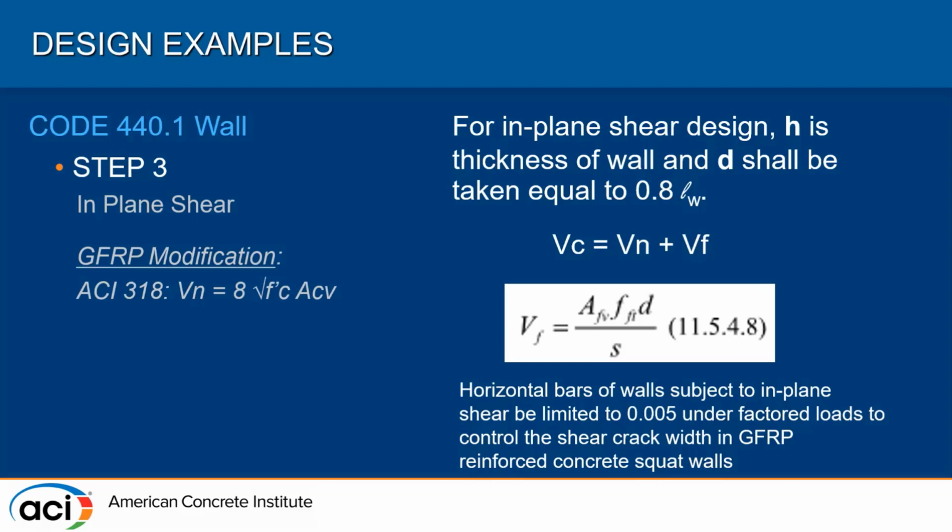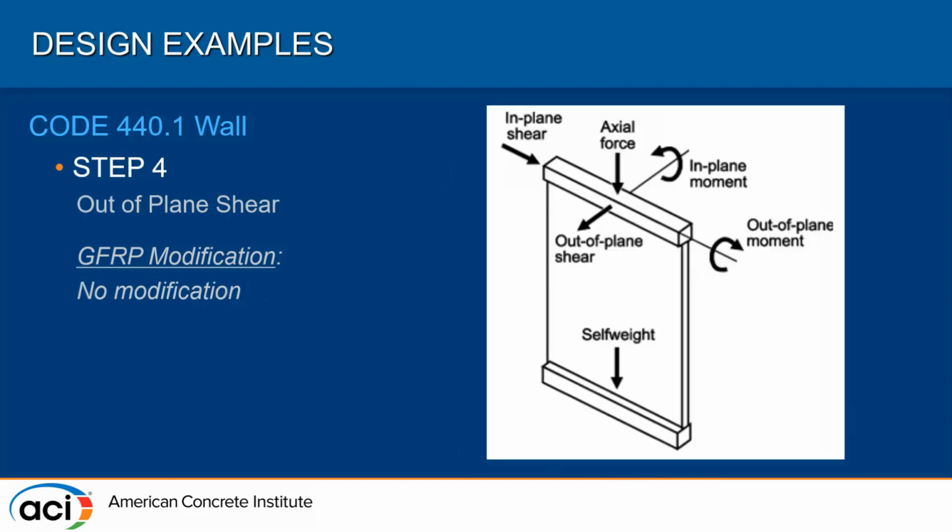It's just 0.005 for the factor for cracks. We're just trying to mitigate any failures in shear. Because everybody knows shear failures are not the mode that we really want to happen. If you've ever been in a lab where they're doing shear testing, you think a bomb went off. So it's kind of scary when it happens. One thing, I kind of put this graphic up here. A lot of the graphics are exactly the same between 318 and 440. If anybody was in the committee, they basically took the 318 and then went line by line and changed or deleted for the 440.